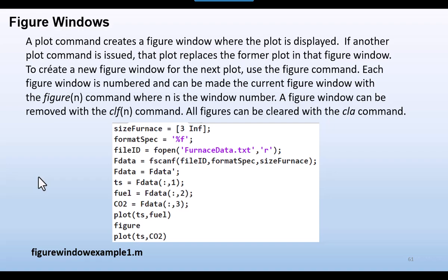Now, if you want to plot two things and have them show up on the same plot without wiping out the first plot command, you can use a command in between them that is called hold on. And if you use hold on, subsequent plots will put the curves in the same figure, all right?